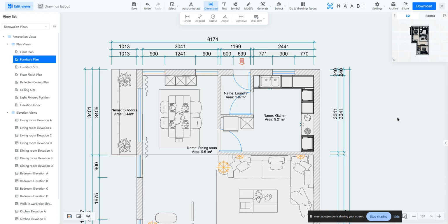The reason why that remaining 10% is remaining there is because the dimension is not a standardized component. Trust me, these factors differ from organization to organization. Just to give you a quick example, some organizations have a practice with regards to custom furniture drawing, cabinets I'm telling. In the external elevation of the cabinet, the majority of organizations have a practice of mentioning the width of the cabinet there. If it is a double door cabinet, they mention the overall width of the cabinet in the external elevation drawing. That is the common standard.